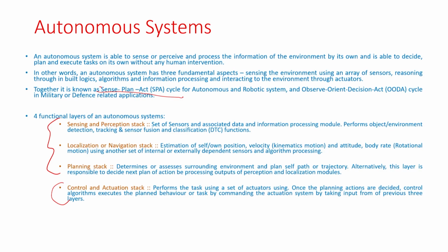You want to capture the surrounding environment of the road. You have small FMCW radars and small cameras, and I will give some examples in the subsequent part of my lecture. You want to take pictures or snaps of the road, how your surroundings look, or consider a mobile robot traveling or moving in a room. What is the vision? It could be some kind of camera or some kind of lidar. It tries to map the whole environment. So, this is your sensing part. What is the planning part?